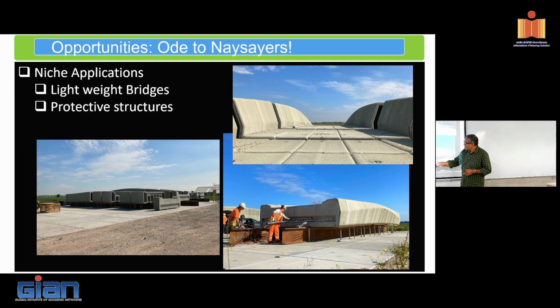And I'm basically able to print these different shapes, right? Every shape here is going to be unique, as you can see here. And it gives you something that is what we call form optimized. So here, the usage of material compared to conventional structure is much less. When I talk material, I'm talking concrete. So that's where this particular technology is a winner, and it can be applied in precasting. Of course, we call it off-site printing, just to distinguish ourselves from precasting.